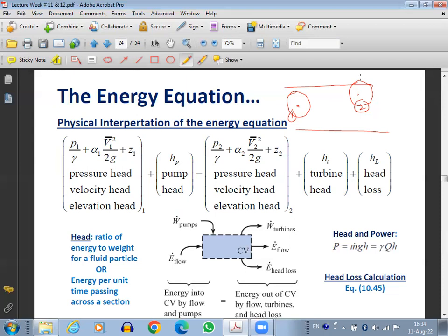Now in the final form, we are also considering the viscous effects. In the Bernoulli's equation, we ignored the viscous effects, but now we are considering them, along with all other factors. Still we are keeping it steady flow, still along the streamline, but we are removing the condition of no viscous effects. And now this is the energy equation. So the energy equation is a further modified form of the Bernoulli's equation in that sense.